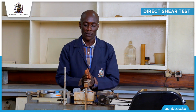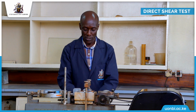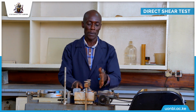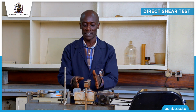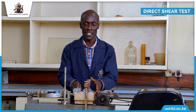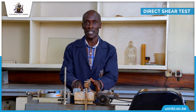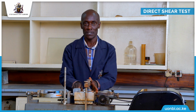Our sample has already failed, so the next step that we are supposed to do is to remove the soil sample from this rectangular box and then prepare another sample ready to be tested under a different load. So the first load that we did was 32.2. The next load will be 68.9, and then finally the third load will be 105 kgs.